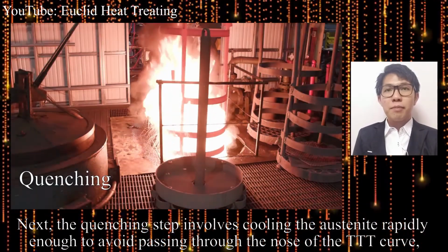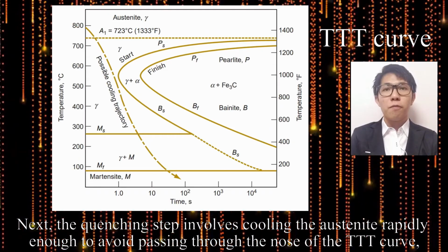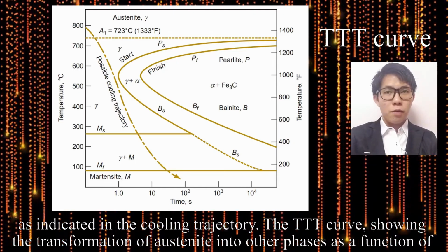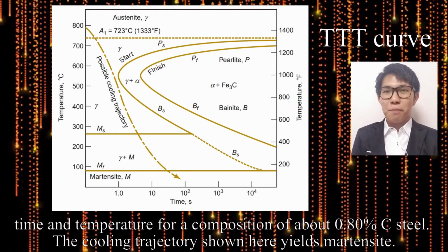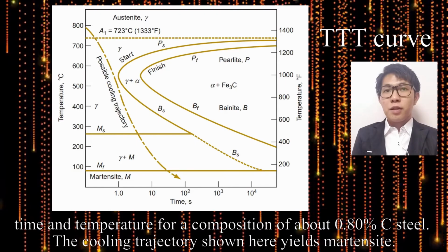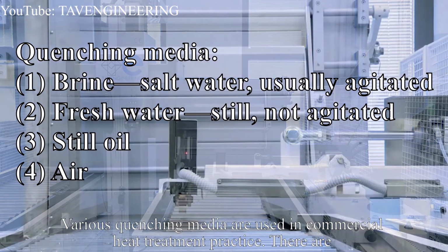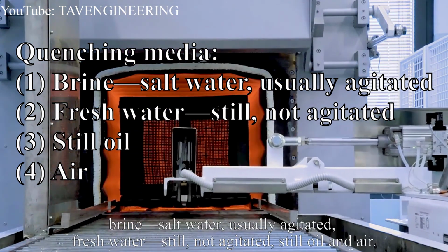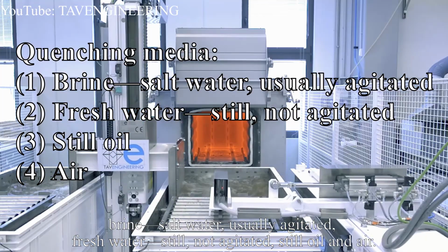Next, the quenching step involves cooling the austenite rapidly enough to avoid passing through the nose of the TTT curve, as indicated in the cooling trajectory. The TTT curve shows the transformation of austenite into other phases as a function of time and temperature for a composition of about 0.80% carbon steel. The cooling trajectory shown here yields martensite. Quenching media used in commercial heat treatment practice are brine, which is salt water, usually agitated, freshwater, not agitated, oil, and air.